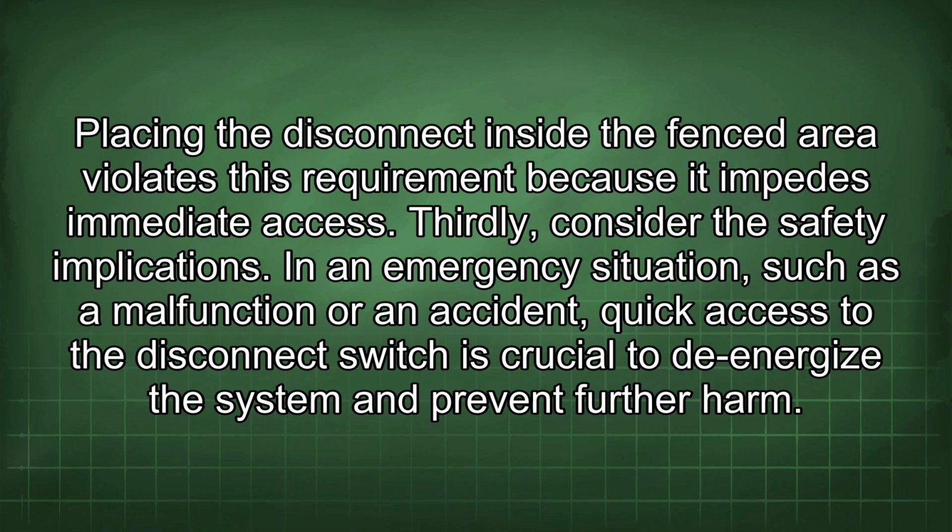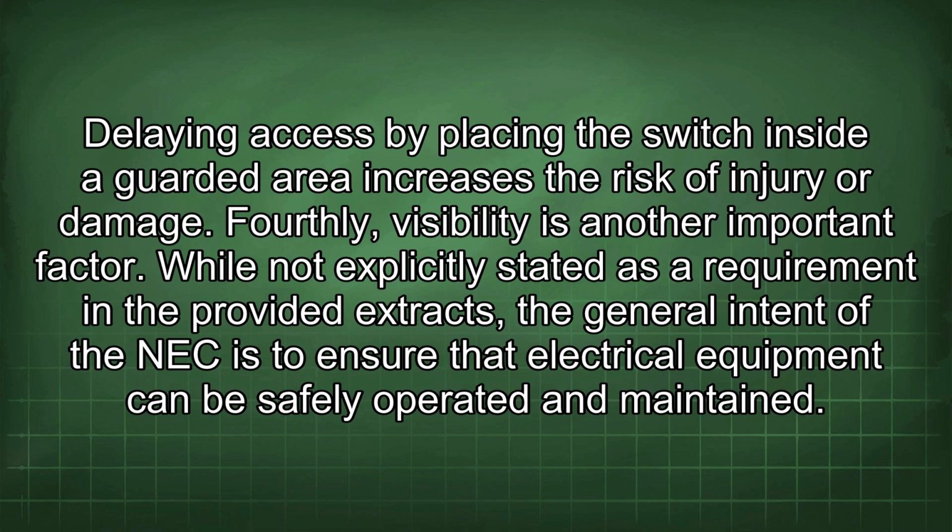Thirdly, consider the safety implications. In an emergency situation, such as a malfunction or an accident, quick access to the disconnect switch is crucial to de-energize the system and prevent further harm. Delaying access by placing the switch inside a guarded area increases the risk of injury or damage.